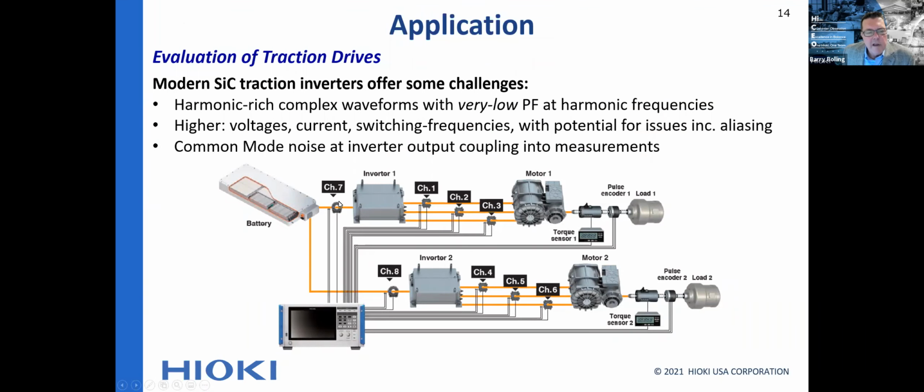But the things that we're facing at each of these inputs and each of these outputs is less obvious. So I'll state them. One is the harmonically rich complex waveform, mostly the voltage waveform, and not a trivial current waveform to deal with. In addition to that, those harmonics form harmonic power, and those pairs of currents and voltages will have very low power factor. And those very low power factor bits of power will be very challenging to measure, and I'll show you why and what kind of care is needed to measure those properly.